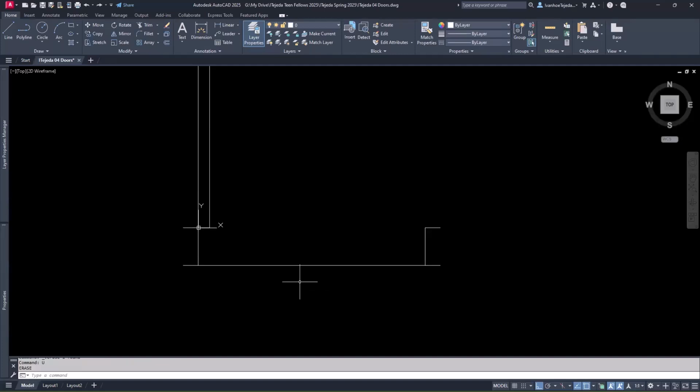I'll undo that. I'll bring it back and I'll undo again. Another way, I can just select the polyline. I can type CO for copy, and I can copy it, let's say, from this endpoint over to this endpoint. Tap the escape key, and then mirror that. So I'll type MI, enter, mirror this polyline, enter, and I'll pick this point here, take it up, and in this case, erase the source object, yes. So I have the results that I had achieved earlier.